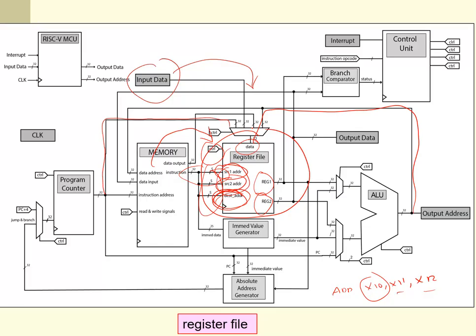So, anything else on writing to memory? It's going to take one of these registers and use it as a base address, and take the other register and write it to memory. I'm just trying to remember which one it is here. It's Reg2. If you look at this, this data is coming over here, and that's what gets written to memory on a store operation. The address goes over to the ALU, which calculates that address, and you can see that come over here for the address.